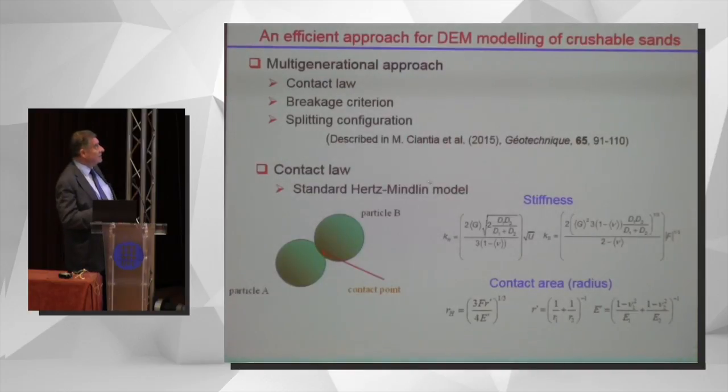as it sounds. Okay, so let me describe briefly the approach that we are using, which is, we think, a quite efficient one. It's been recently published in Géotechnique. First, I'll mention the contact law that we are using, which is an essential part of this method, but then concentrate on two things, the breakage criterion and the splitting configuration. For the contact law, it's a standard Hertz-Mindlin model. These are the expressions for the stiffness, normal stiffness, sliding stiffness, and the evolution of the radius as you increase the force. So this is pretty standard, but these are the actual contact laws that we use.